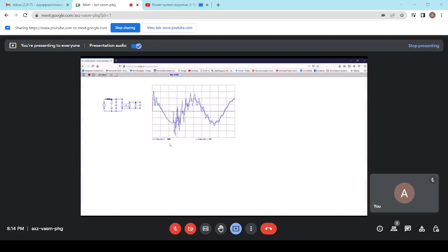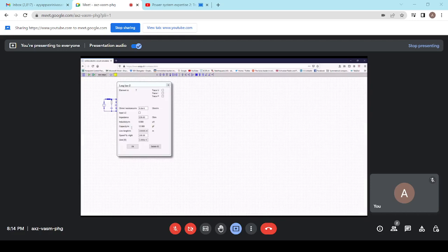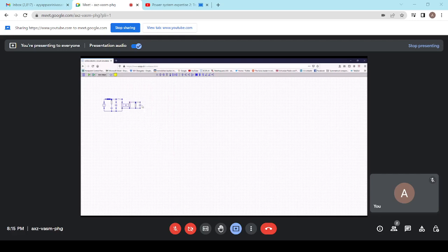You can see now that the breaker closes here when the voltage collapses across the breaker, and at the end of the line you now have an overvoltage. The situation can even get worse if I have a pre-charged line with trapped voltage, and the same trapped voltage should be in the capacitor here.